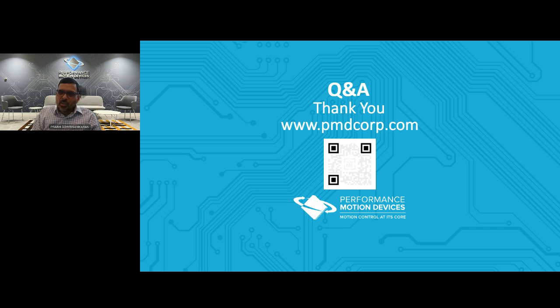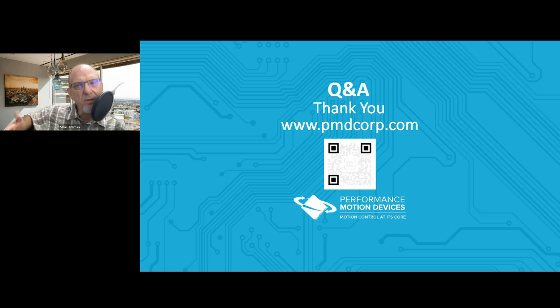And the other advantage is you can actually mix and match drives and chips. So we have had one customer that has put an N series drive on there as a master, and they put chip-based stuff for remote axes that are smaller axes, lower power output kind of stuff. So you can synchronize across our products. There's a sync signal that synchronizes between the chips. So theoretically, then you could put a motor on a conveyor topper on top of a mobile robot that would also be controlled and synchronized. Correct.